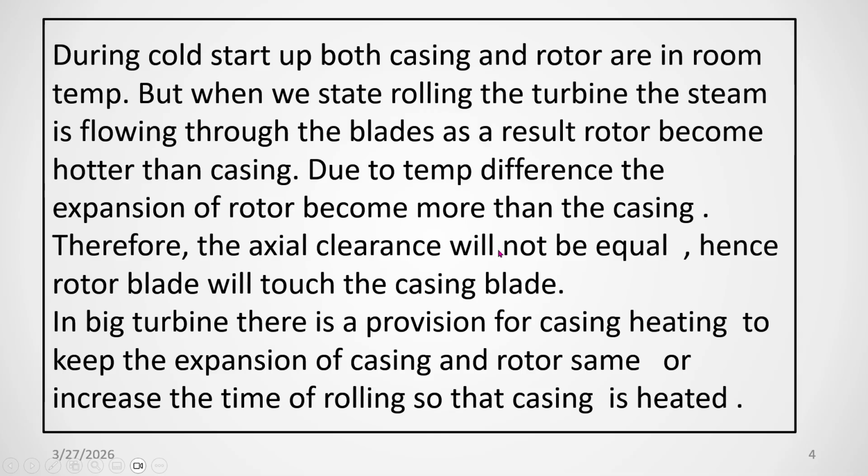So in the big turbine, because it will take at least more than 1 hour to get the casing temperature the same, what we are doing is introducing some steam into the hollow section of the casing, so that the casing comes in direct contact with the steam and also expands in a similar way to the rotor. So there are equal clearances, and the differential expansion will remain the same. So there should not be any chance of touching.